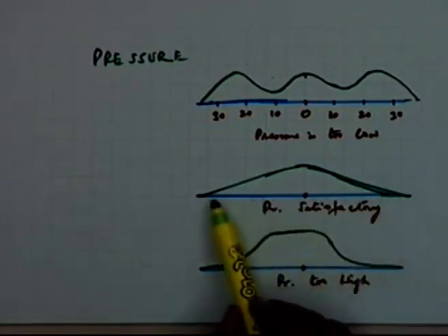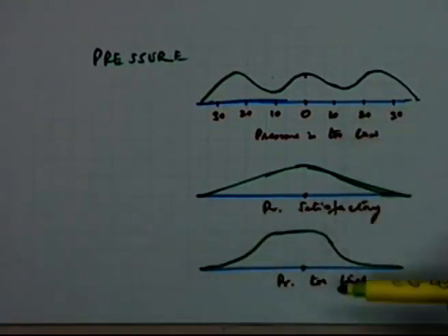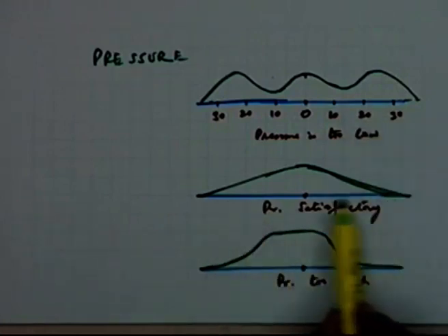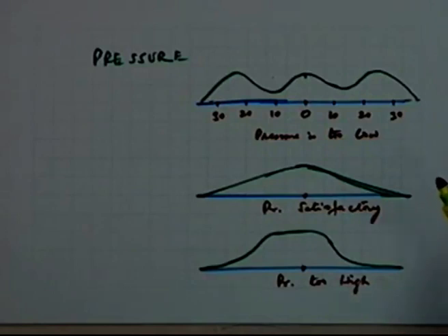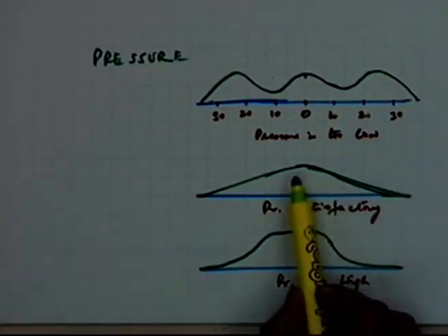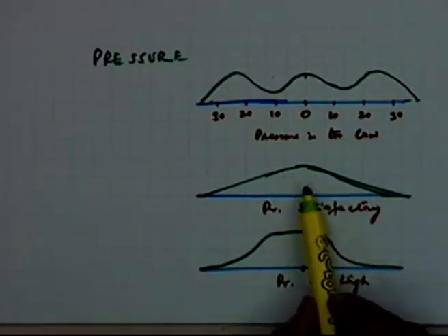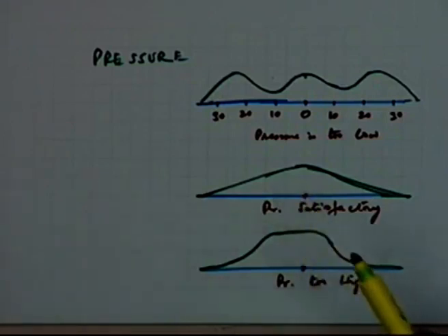Whereas under some in-between pressures, you will get a more triangular type of distribution, and this distribution is more suitable because ultimately you want to overlap these individual distribution patterns and get a uniformity which is quite high.